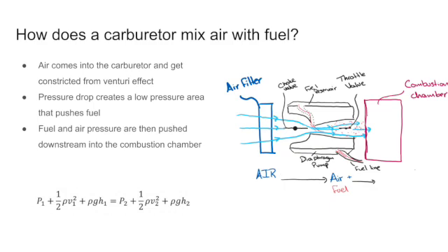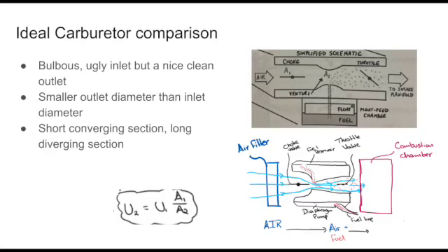The pressure drop created in this vacuum-like area pulls the fuel from the reservoir inside the carburetor through a small hole called the jet. There, the airflow gets restricted and the flow becomes a gas-airflow mixture, ready to supply the engine of the chainsaw. The speed at which the fuel is flowing is also determined by the pressure drop from the Venturi tube and ergo the airflow. The main airflow is then finally determined by the throttle.